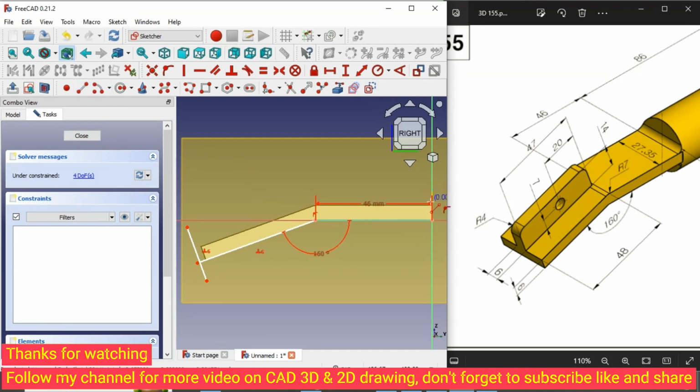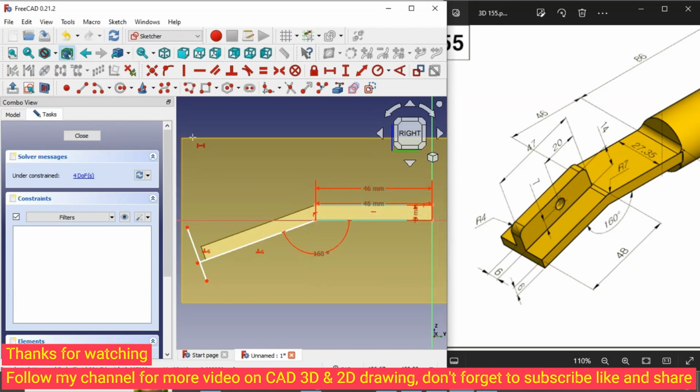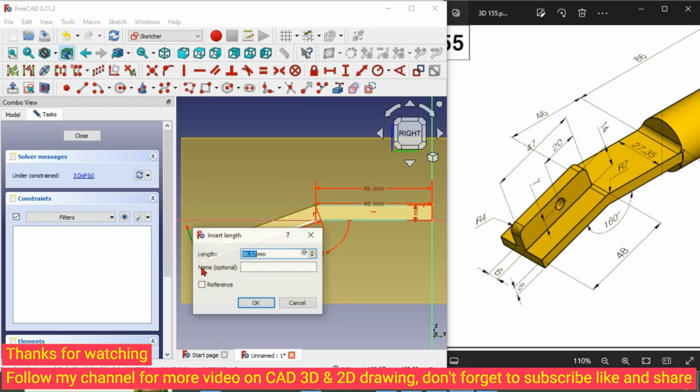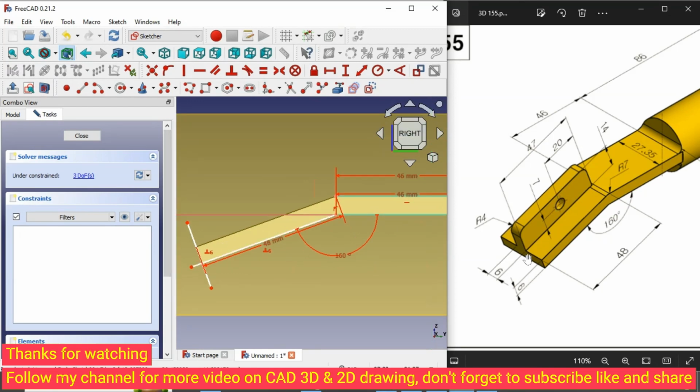So we need to draw a line here, then we set the height to center reference will be 6. Then this line we constrain to this center line here, then we set the distance, so 46. Okay. Distance from here to this line is 48. See? Okay. That's why we need to draw it, but later we need to delete it back. So okay,